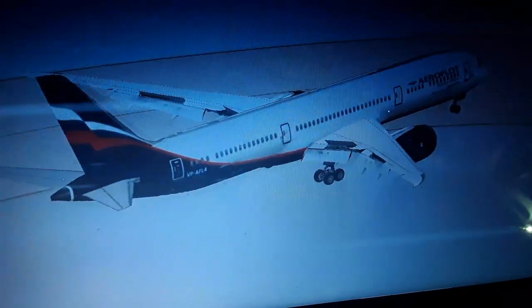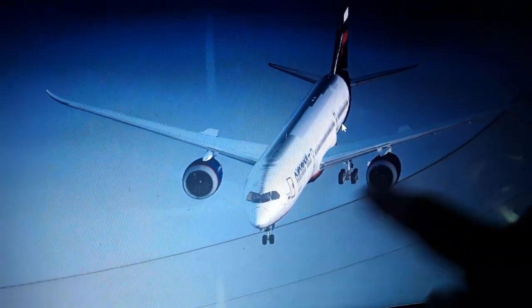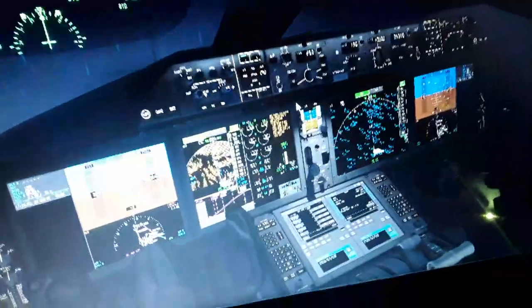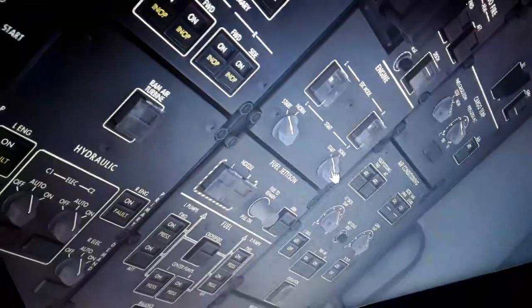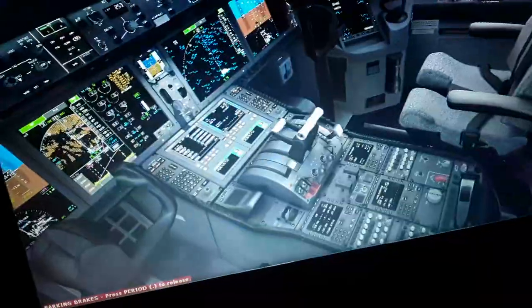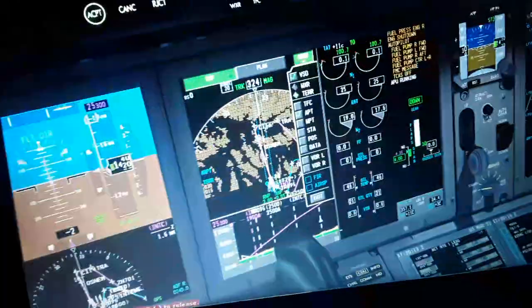So this will make the engines of the Boeing 787 come to a stop. You can see also the hydraulics are having no pressure. So we're going to start the auto start here. You can see these switches. We need to get them to the start position, as you can see. So we have the auto start now on. You can see the resets and the overhead panel with yellow, and also we're going to have pressurized air from the APU being automated very quickly.